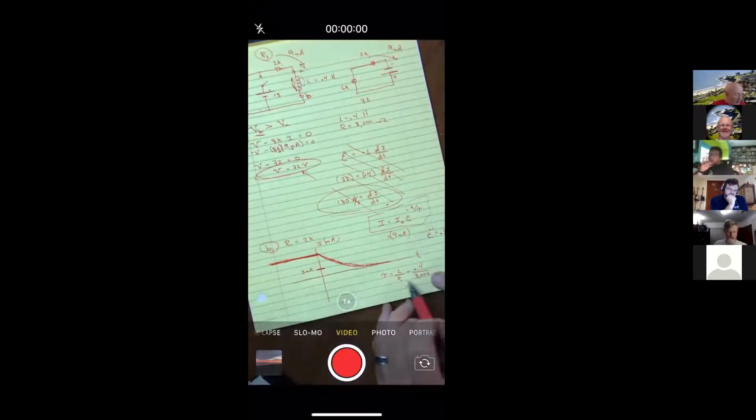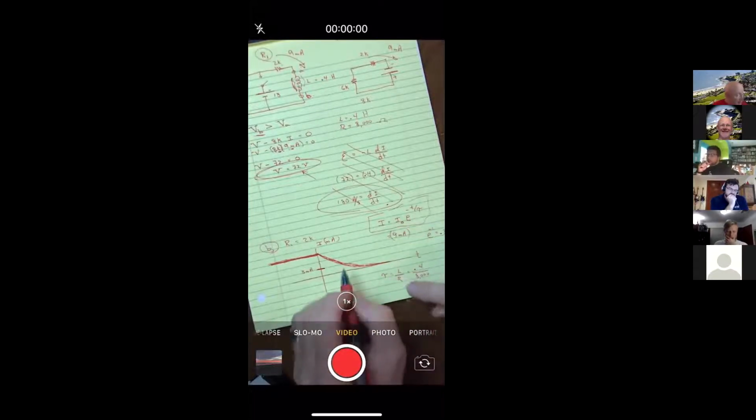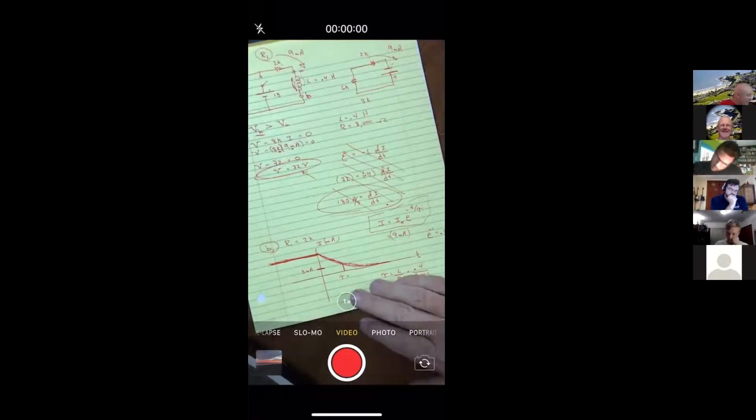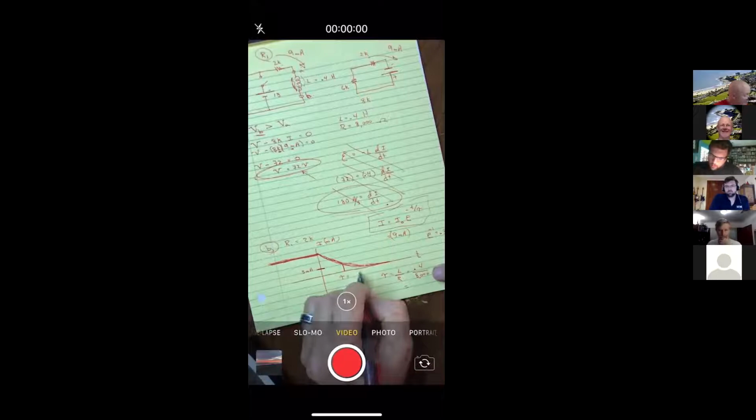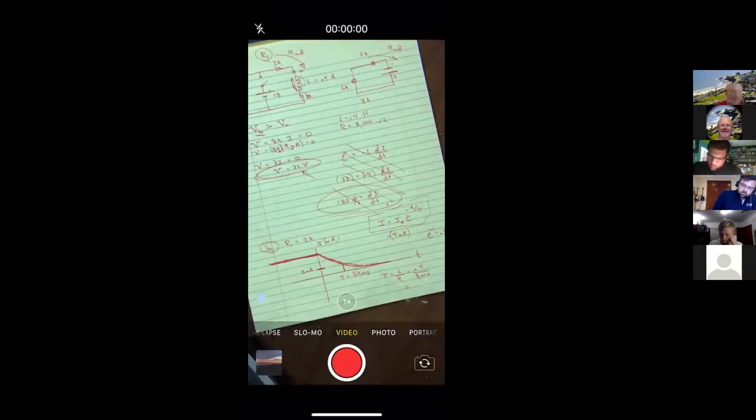Okay, so in about one decay time, so when the time is equal to the decay constant, I would get e to the -1, and that would be multiplying 1/3 by about 9. So this right here on the time axis would be one decay constant, which would be about 0.4 divided by 8,000. So this would be about 50 microseconds. So again, if I was kind of freehand sketching it, I guess that's what I would do there.